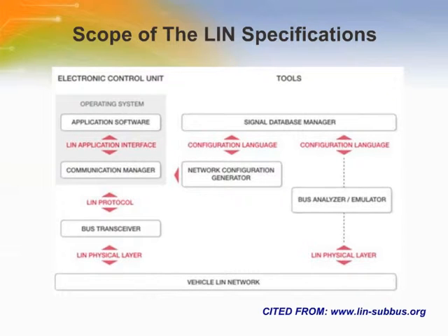The LIN standard encompasses the specifications of the transmission protocol, the transmission medium, the interface between development tools, and the interfaces for software programming. LIN guarantees the interoperability of network nodes from the viewpoint of hardware and software and a predictable EMC behavior. The protocol specification describes the data link layer of LIN.